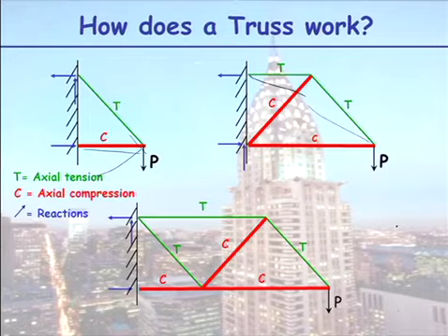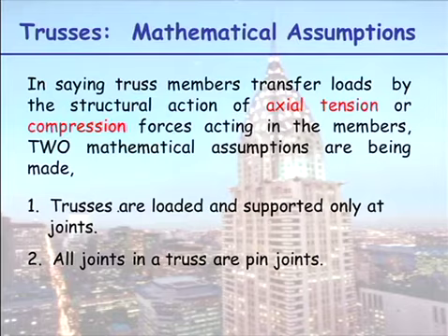how trusses work. So you can see here this P force effectively is coming up this member, then it's going down this member, and then it's coming up this member, and it's been restrained up at the top support here. So the loads transfer through all the members. Okay, you can't say it's just going up that member and across. So the loads can't go from a vertical component of load to horizontal. So they need every member in the truss to work if it's a determinate structure.